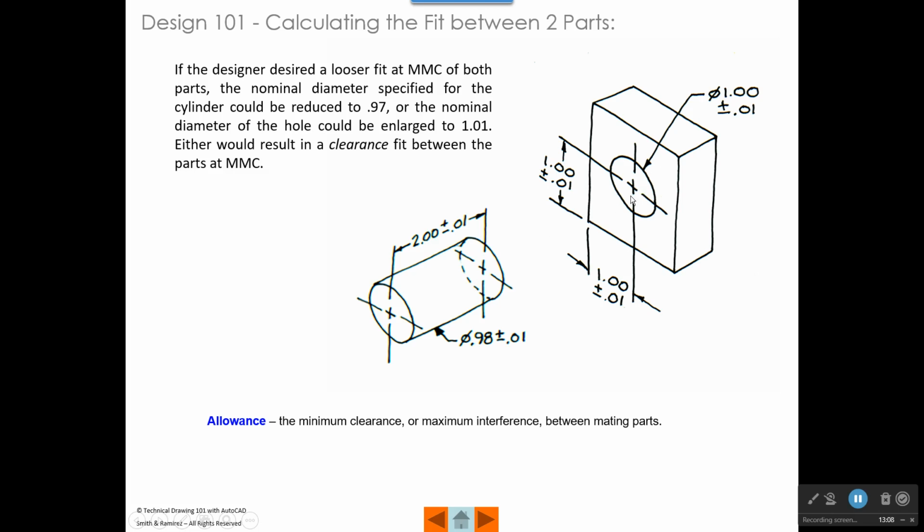And by pressing it through, it might jam this in there, and it might be a way of attaching this cylinder to a part without welding it or molding it like that. And so sometimes we want an interference fit, and sometimes we want a very loose fit, and sometimes we want a fit that's just a sliding fit that will allow it to clear but slide through pretty easy but not have a big clearance in it.